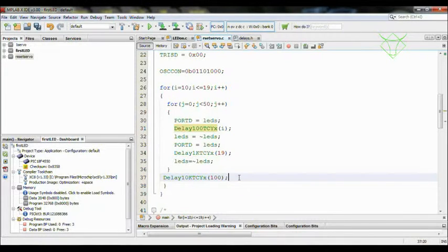The servo is sweeping from 0 to 90 degrees. Sorry, 1 millisecond to 2 millisecond, whatever I'm generating, it is sweeping from 0 to 180 degrees. That is what I'm trying. So I'm just making a delay, and again it will come here and increment. In this for loop I'm increasing the positive pulse. The i which is here varies from 10 to 19, which means I'm generating 1000 ticks to 1900 ticks.